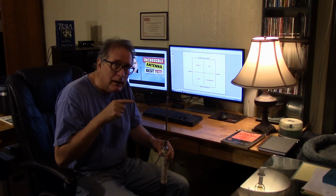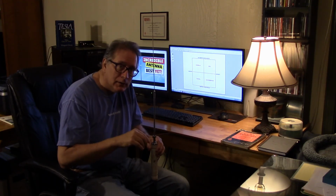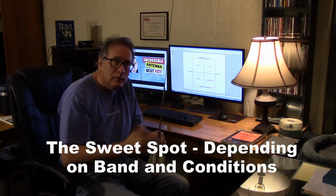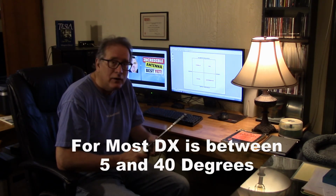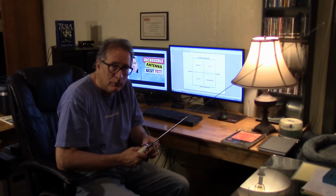The quickest way to cheat the system, in effect, and get a low angle of radiation is to use, as the antenna commander says, a vertical antenna. A vertical antenna, by its nature, gives you the best chance for a low angle of radiation, and it's all done through physics. It's natural. So as you improve your radial field, your signal continues to lower, and you're going to get the DX. So that's a very simple way to maximize your DX performance: use a vertical antenna.